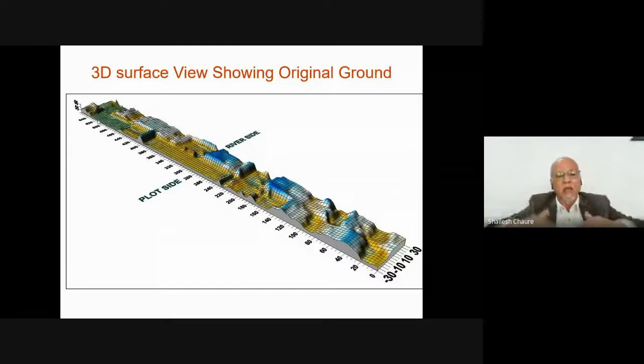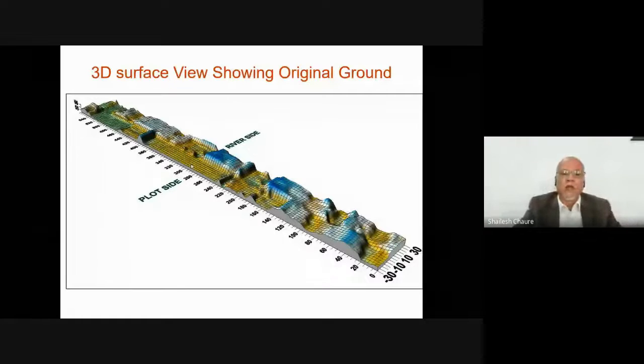Now you can just manipulate the pixels or the values in this area, and can increase the elevation. So once you increase the elevation, the surface will reappear, will look quite different. So how a thing will be seen after a cut, how the thing will be seen after a fill, you can just visualize well before filling it or before cutting it. Or you want to modify a surface in a certain way, you can have a computation, a digital model of that surface, and you can integrate it with the original digital elevation model before the construction.